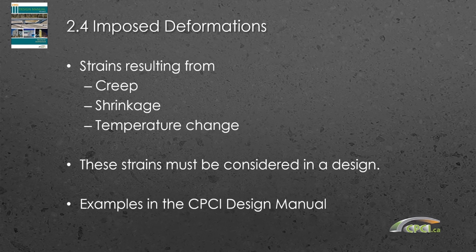Obviously, concrete is shrinking as it loses moisture over time, and those strains need to be taken into account. Either an increase or decrease in temperature will make precast concrete elements expand and contract, and all of those features need to be considered in the design of a total precast structure.